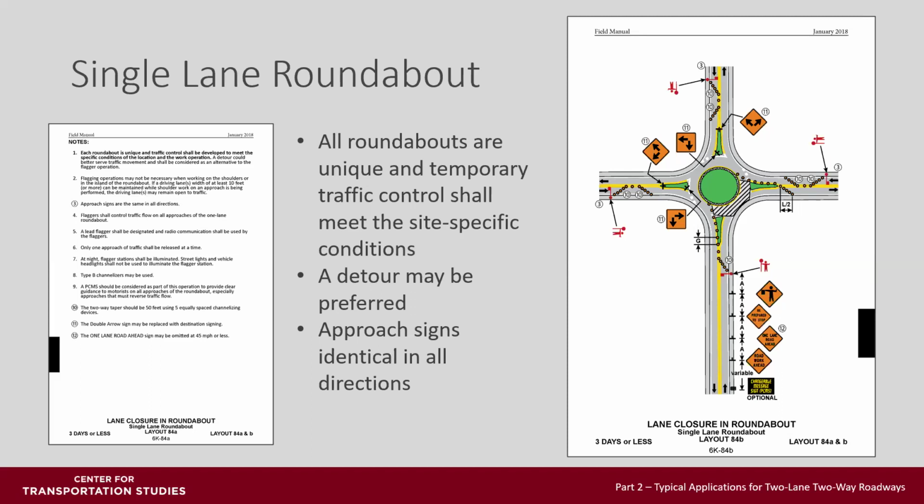As you notice, it takes 4 flaggers. They need to coordinate very well. You're directing traffic to go basically the wrong way through that roundabout, which might be difficult depending on the splitter island designs. For instance, if you're going northbound here and someone wants to turn left, that splitter island might be very tough for a vehicle to make that left turn at that location. So it's not a very simple thing to do this.